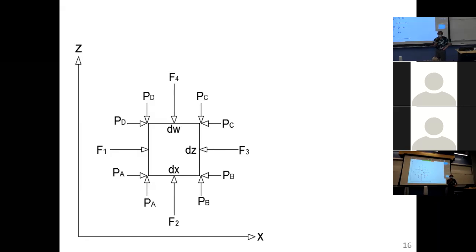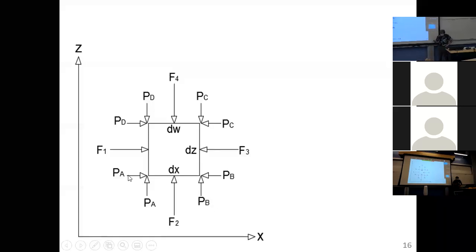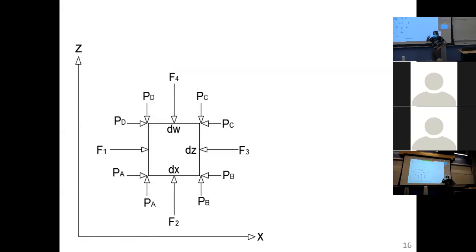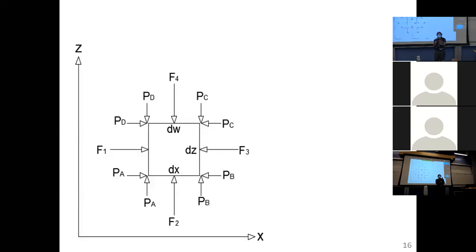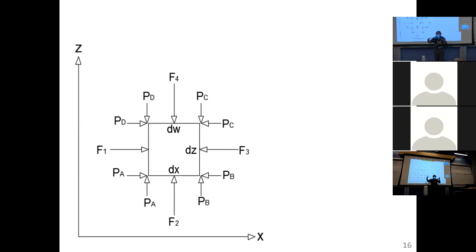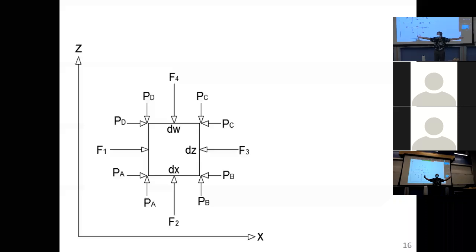So if we do a two-dimensional analysis, whatever we find for the X should be for Y. And then what we did was, in this little cube, now a 2D element, we assumed that pressure varied over the outside of this. And again, that represents the fact that we took this little cube and removed it from the fluid, and these pressures acting on the outside represent the rest of the fluid that's really out there.